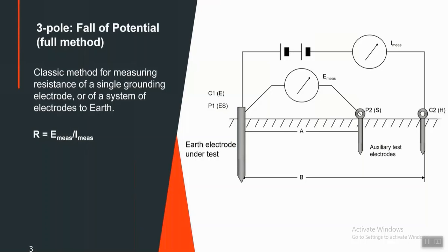The instrument will automatically step through its measurement range, and use the generated voltage to calculate and display the system resistance in a range from 0.001 ohm to 20 kilo ohm, depending on the instrument tester.